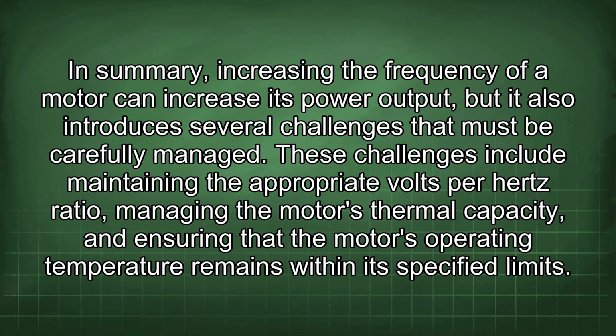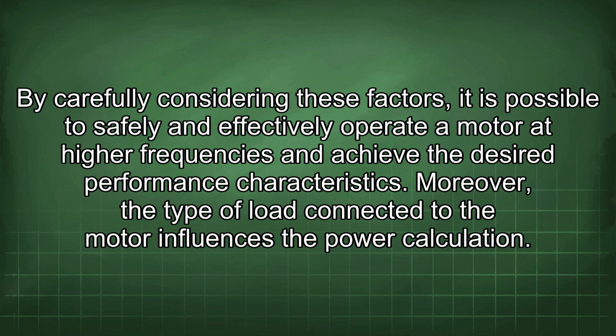In summary, increasing the frequency of a motor can increase its power output, but it also introduces several challenges that must be carefully managed. These challenges include maintaining the appropriate volts per Hertz ratio, managing the motor's thermal capacity, and ensuring that the motor's operating temperature remains within its specified limits. By carefully considering these factors, it is possible to safely and effectively operate a motor at higher frequencies and achieve the desired performance characteristics. Moreover, the type of load connected to the motor influences the power calculation.